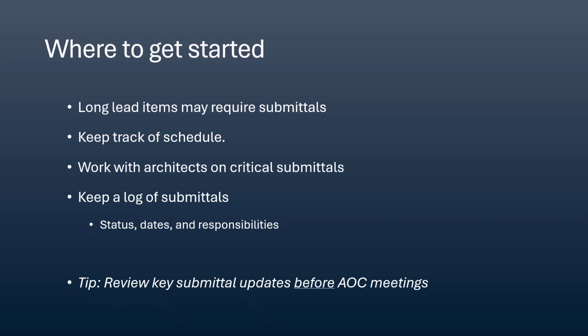But keep a log of all your submittals: what's happened, what's currently happening, who has the responsibility of the submittal. If I've had to resend it to my subcontractor, I need to keep note of that, or if I have something to do before I can send it to the architect, that should be noted. And then also dates, especially dates on when the submittal has to be processed.